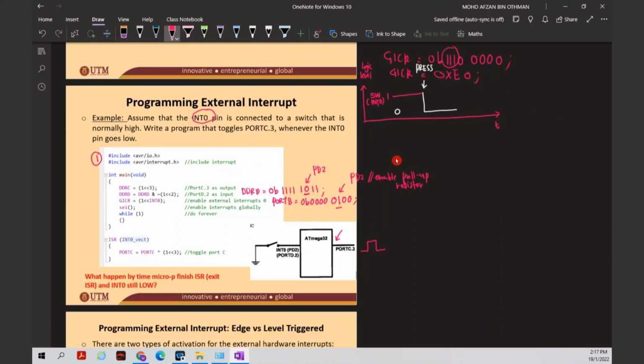Okay, this will help, because your pin D is normally high, so it will give the pin D here, pin number 2, the value 1. So this is what happens here, and this is step number 2. Step number 3, you need to enable the interrupt register.